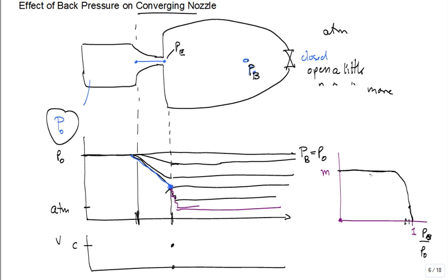The flow is choked at the throat. The flow is choked at the exit. So afterward, you'll have a shock, but that doesn't help you increase the exit speed or the mass flow rate through that nozzle, does it? Not at all. Okay? Sorry?